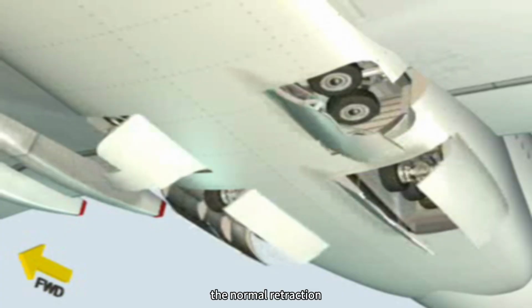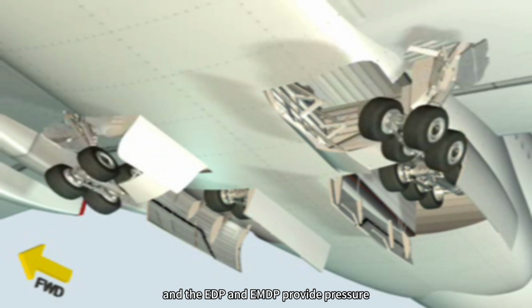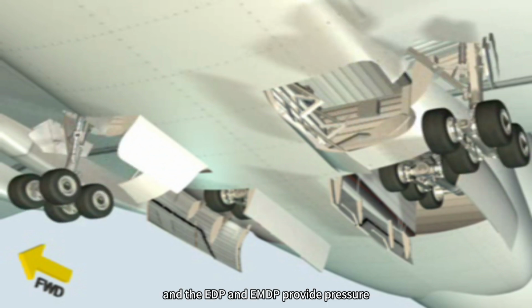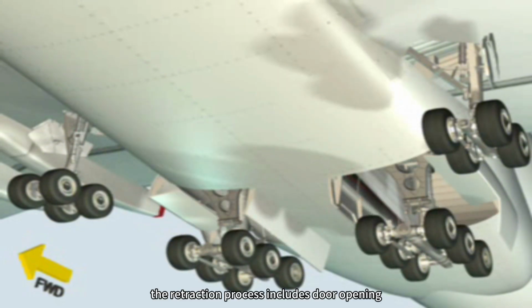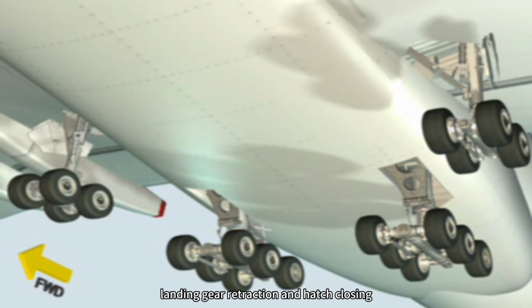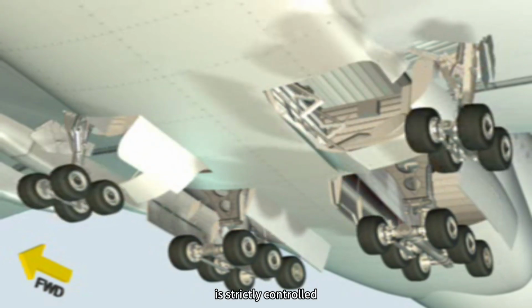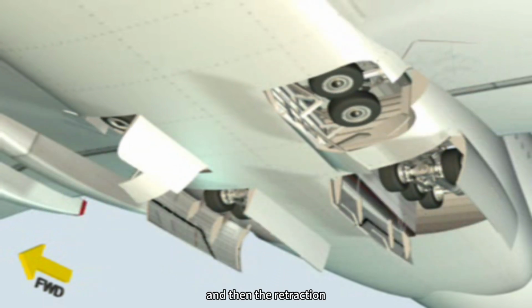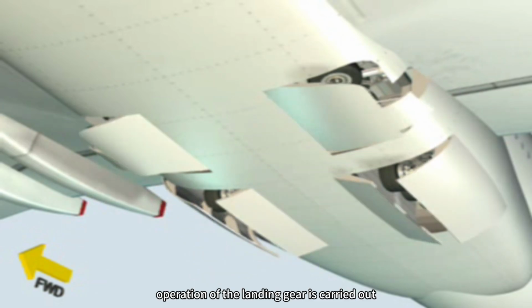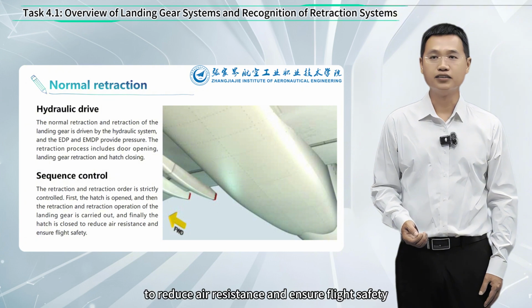The normal retraction and extension of the landing gear is driven by the hydraulic system, and the EDP and EMDP provide pressure. The process includes door opening, landing gear retraction, and hatch closing. The order is strictly controlled. First, the hatch is opened, and then the retraction or extension of the landing gear is carried out. And finally, the hatch is closed to reduce air resistance and ensure flight safety.